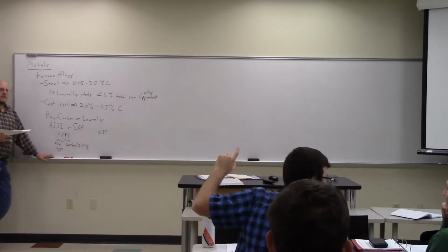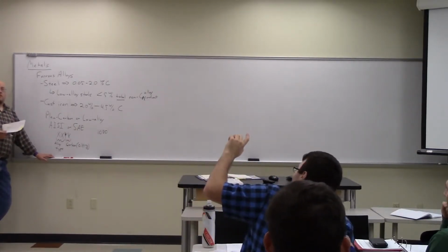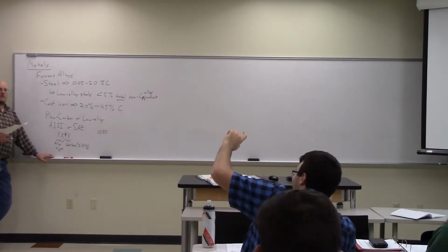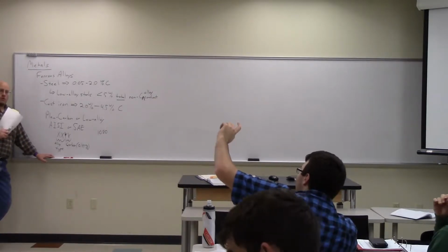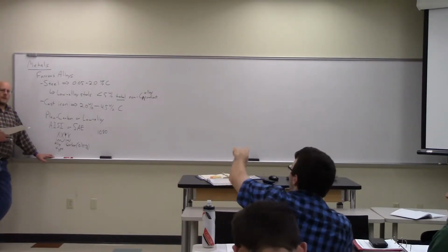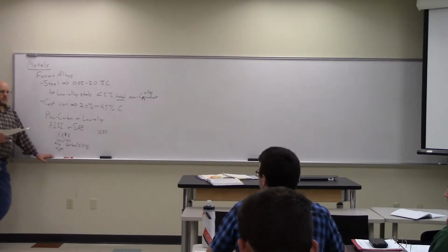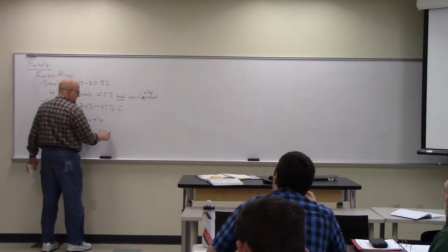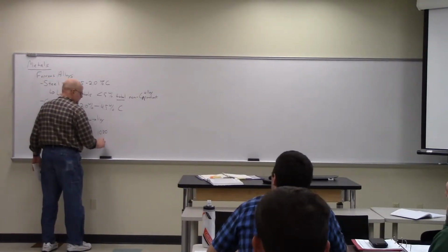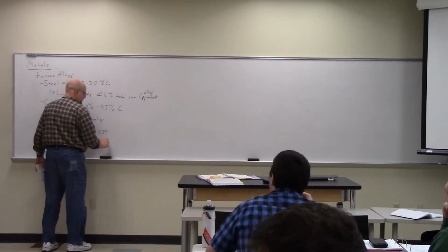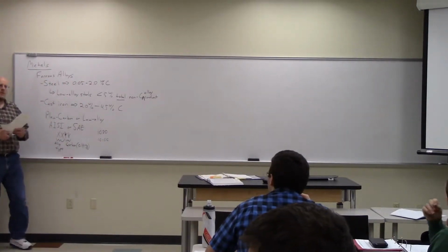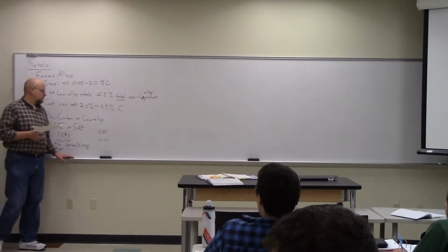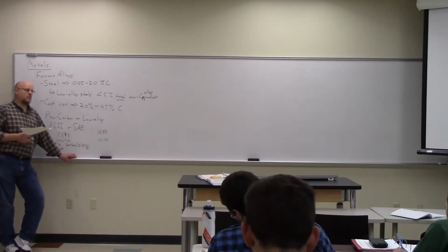What would not be a eutectoid steel? 1040 steel. So a 1040 would be a hypo-eutectoid steel, yes. What do you do if you have something over 1%? You'll add an extra digit. So for 1.5 weight% carbon, we had 10150. 10 means it's just plain carbon.